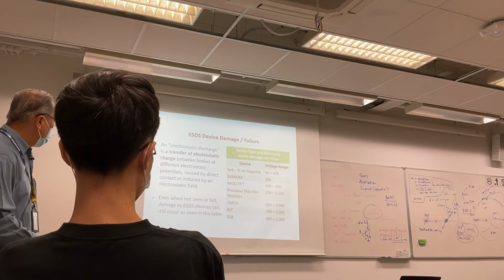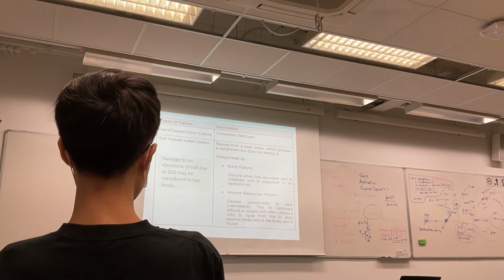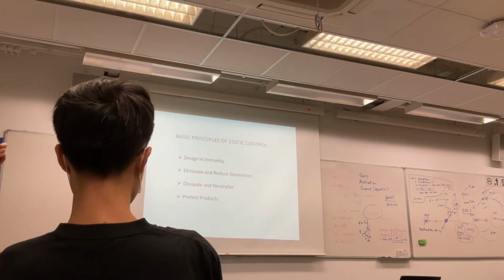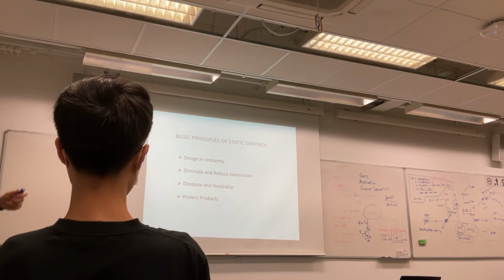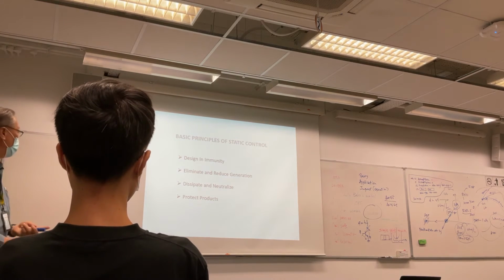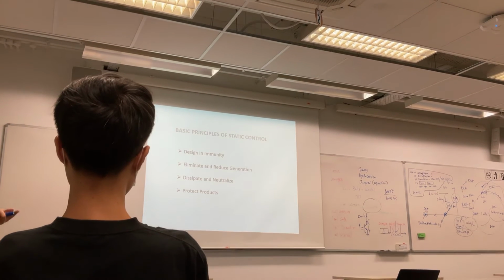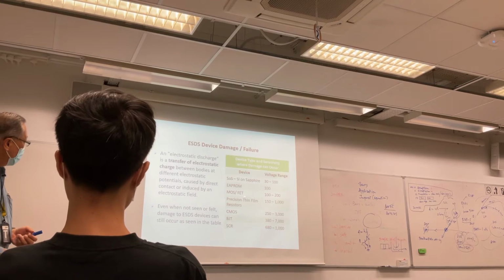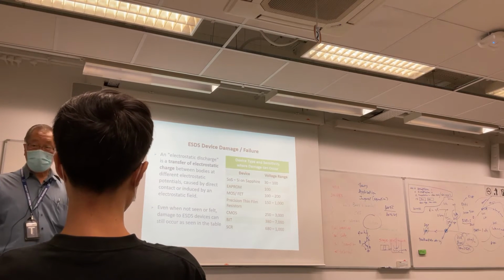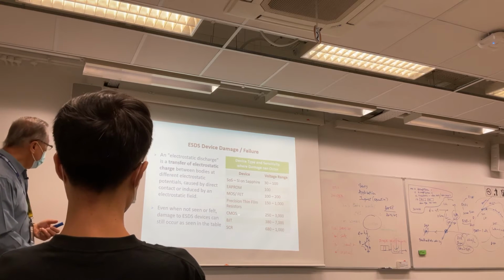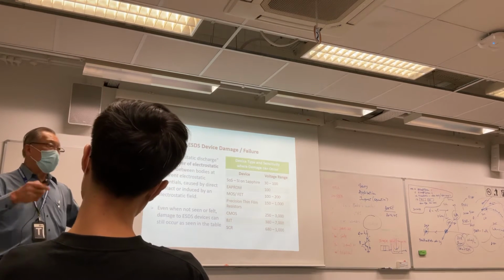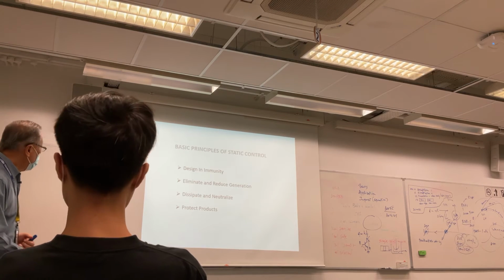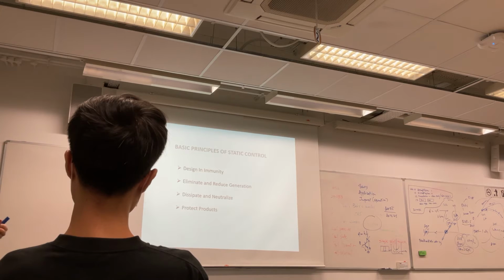Okay, so these are the things that we went through. These are the early failures I mentioned to you, altered response pattern. This is important. You need to know the basic principle of static control. The question may be asked: design immunity. That means when you design, if you use a FET, you have to be very careful with electrostatic discharge. But if you design with a BJT, you don't have to overdo it. Depending on what you're using, design immunity is very important. You have to understand and protect it.